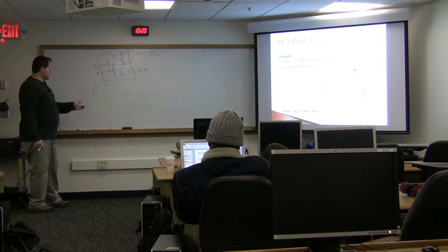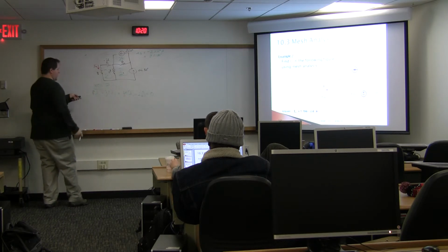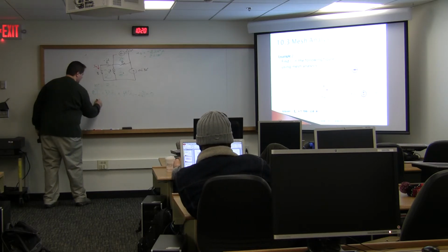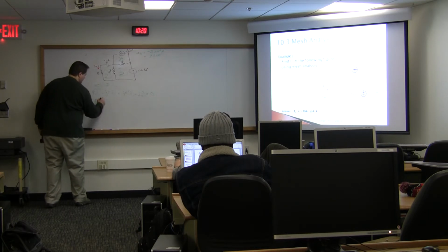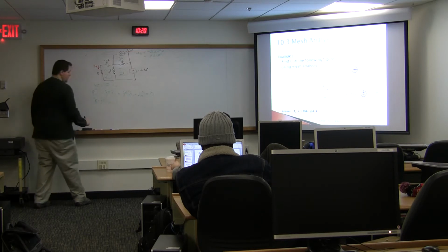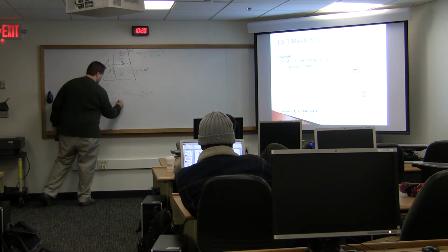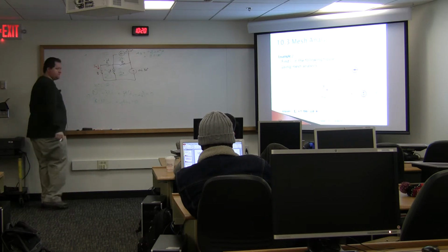And now I can clean this up, put it into a standard form, collecting my like terms. So I have 8 minus J2 plus J4, so that's 8 plus J2 times I1, and then my I2 term is just negative J4 I2 equals 0. And there's my first equation.